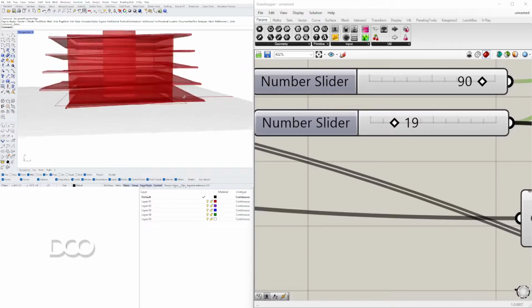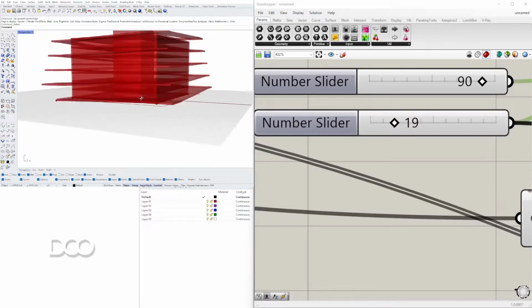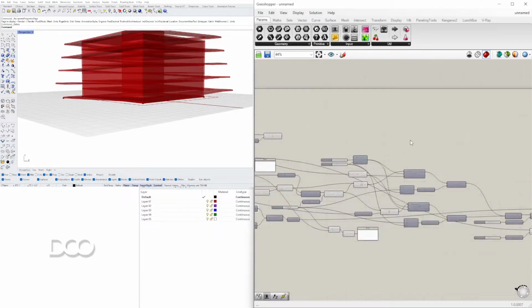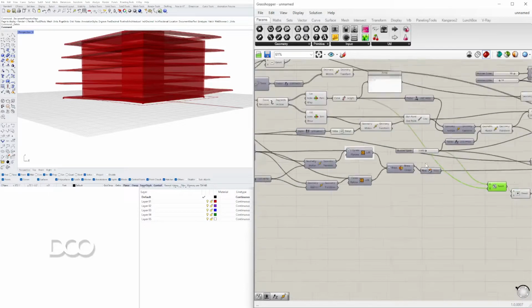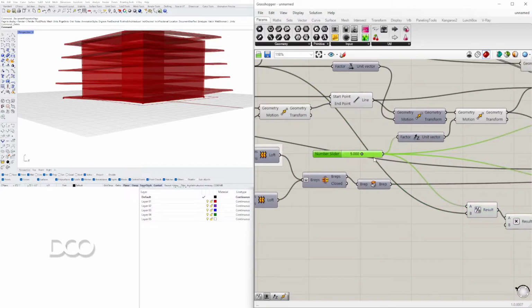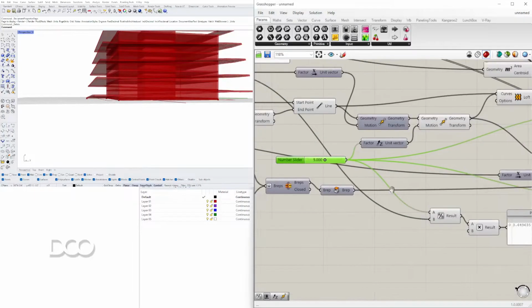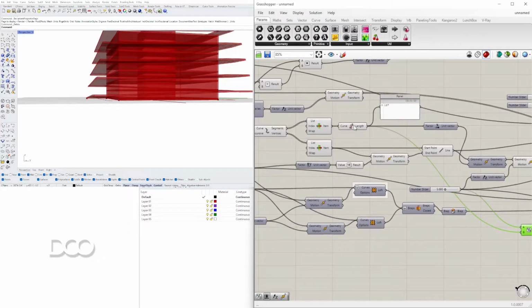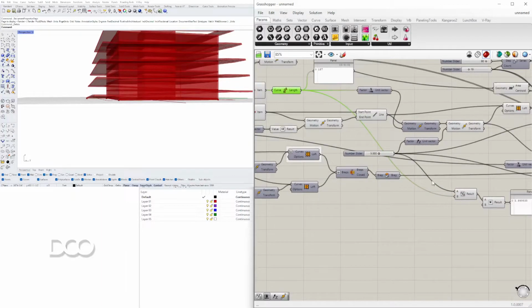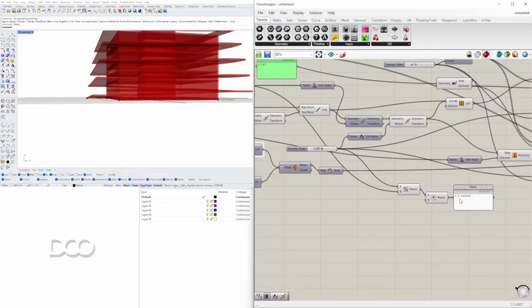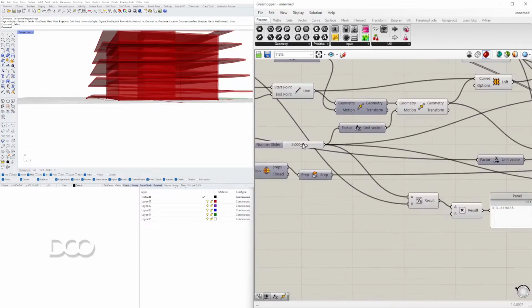Something like this, where we can go up the ramp, make sure that it's within. So we have going up 5 feet from beginning to the end. The length is, rise 5, run 137. That gives us this percentage, which means that we can actually probably go up more.